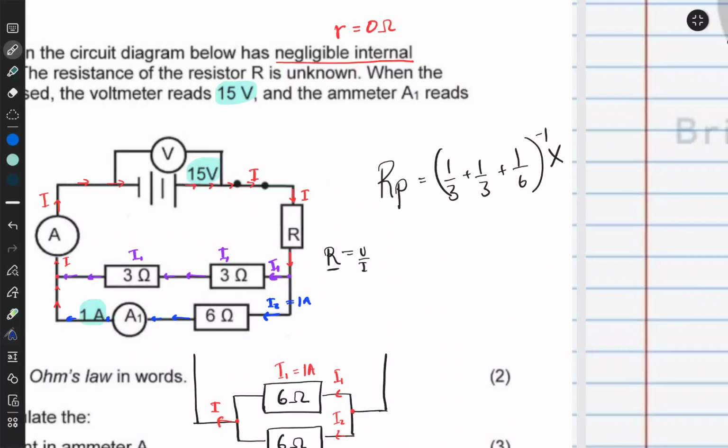Right. So how you want to think about it is they must go in pairs. If maybe there was another resistor here, let's call it a 4 ohm resistor, then you could do that. You could say 1/3 plus 1/4, right? That's my first pair. And then 1/3 again plus 1/6. That would have been my second pair.